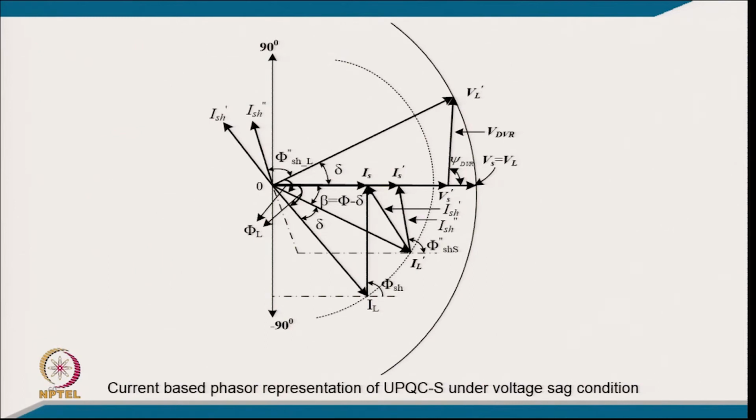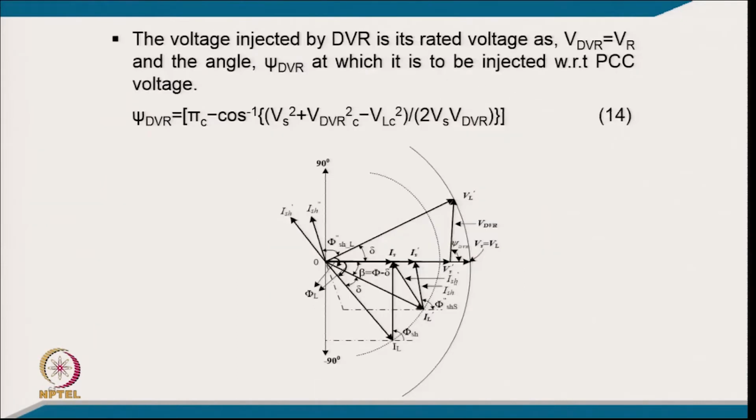representation of voltage sag compensation. So, you can see earlier it is, let us say, the voltage, but once sag comes you inject the voltage here by DVR, and that is the new voltage across the load. And of course, when this voltage goes up, in that case you will find with respect to the load voltage, the source current becomes in phase with the source voltage, because you want to have a D STATCOM. So, even the rating of the D STATCOM is partly reduced in that case, and that load is virtually transferred partly to the DVR.